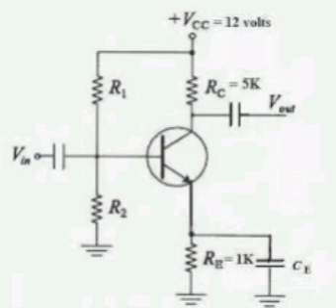Second question: the output of an LVDT is connected to a 5-volt voltmeter through an amplifier whose amplification factor is 200. An output of 2 mV appears across the terminals of the LVDT when the core moves through a distance of 0.5 mm. Calculate the sensitivity of the LVDT and that of the whole setup. The millivoltmeter scale has 100 divisions. The scale can be read to 1/5 of a division.